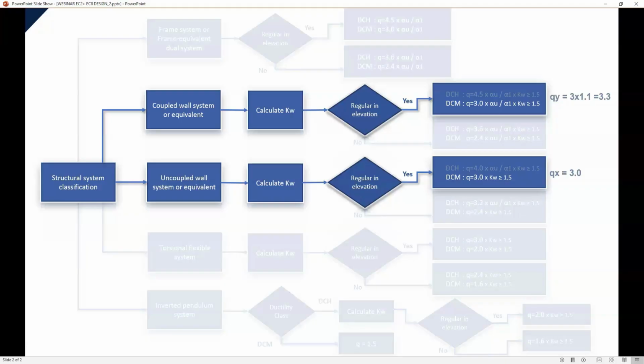The main rule, in addition to all the others we have verified so far, states that the contribution of the secondary elements to the bending and shear stiffness in all stories of our structure must be less than 15% of the stiffness of the primary structure. This means that if we initially chose a very broad set of secondary elements, it is possible that by this phase, after checking regularity in plan, regularity in height, and other rules, we might find the secondary element's stiffness contribution is greater than 15% of the primary structure. So, the question is how we are going to check this in our building.